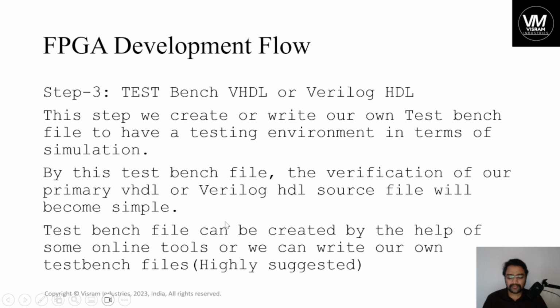Now we can make test bench files by using online compilers available in the market, but the highly suggested methodology is writing the test bench on your own. Understand how to write test bench vectors or test bench files for your primary design source file, which is HDL. Based on the primary HDL file, you can generate the test bench VHDL by using online tools or by writing it on your own. In our industry, we don't want to compromise our own primary source design file in online compilers, because we shouldn't be giving the company's data to outsourcing. Hence writing test bench VHDL files or test bench vectors for our own primary source design file is a most required skill.